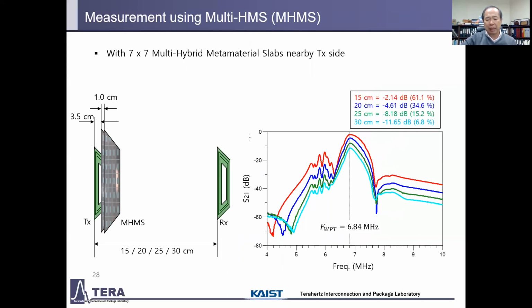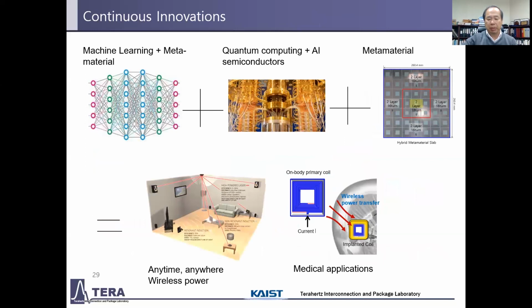So our idea is that in the natural world, there are certain materials, air, dielectric and ferrite, that are useful for certain applications in wireless power transfer systems. But however, we can make artificial materials. So today our two subjects are artificial material and artificial intelligence. Using this artificial material called metamaterial, which has negative or 0 magnetic permeability at certain frequencies, not all frequencies, if we design this metamaterial well, we can utilize those properties of zero and negative magnetic permeability. This is the conclusion of my presentation.